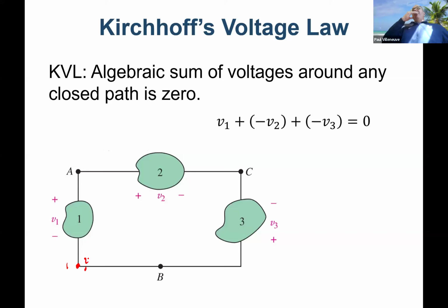Now, again, this is another thing where I need everybody to understand there are 2 ways to do this. Item number 1 is the sum of the voltage drops equals 0. Or item 2, the sum of the voltage rises equals 0. They're essentially the same thing, but it's important that we understand which we're using, because when we identify conventions, pluses or minuses, we use a different approach.